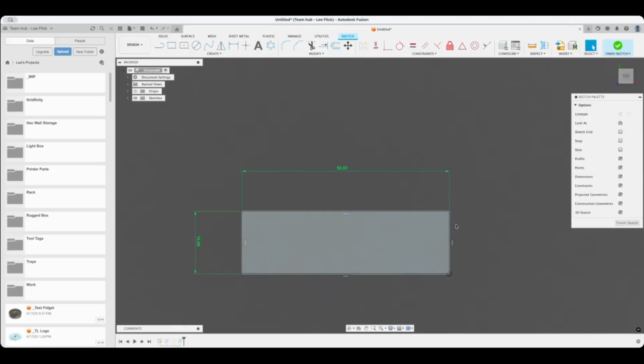Okay, so did you add them originally? Do you remember? I don't know, I just dragged it out. Let's add them then. That's probably the thing. She came out of the sketch menu. You can always go back and add them. So up in the menu bar is the dimension tool, the Sketch Dimension.